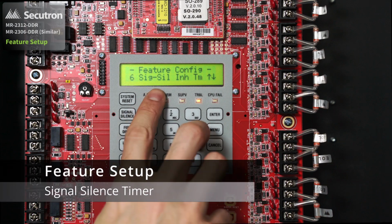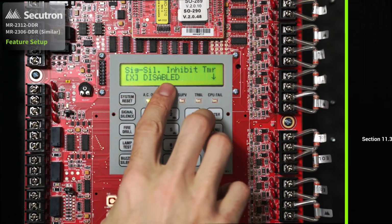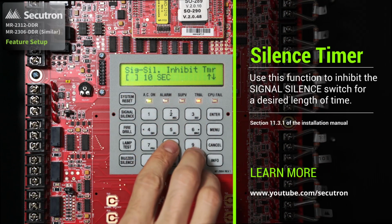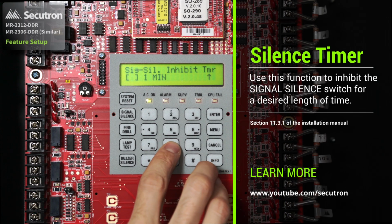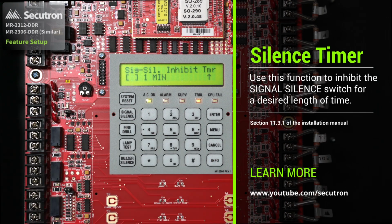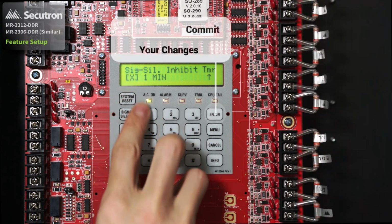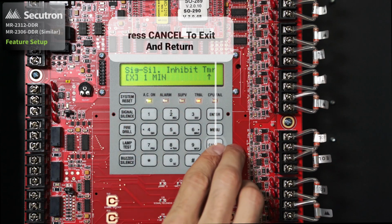The next feature is signal silence inhibit timer. By selecting Enter, we can see that it has been disabled. If we scroll down, we can set the desired time of 10 seconds, 20 seconds, 30 seconds, or 1 minute. This function inhibits the signal silence switch for a desired length of time; this time period should expire before the signals may be silenced. Right, so if we wanted to select 1 minute, we apply the X. Now our signals would not be able to be silenced until the 1 minute has expired.